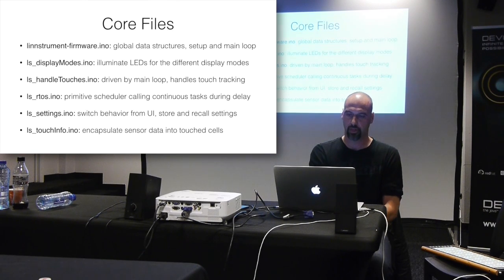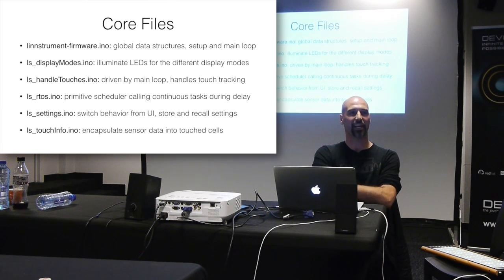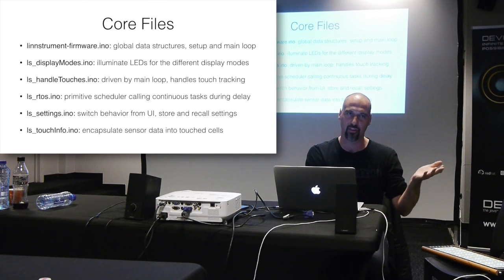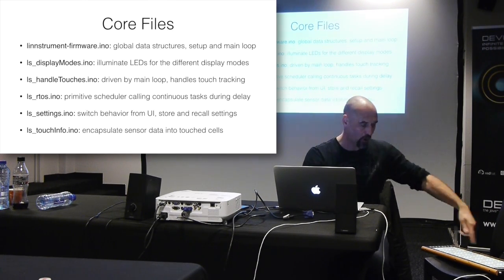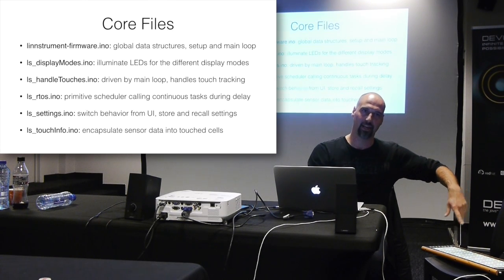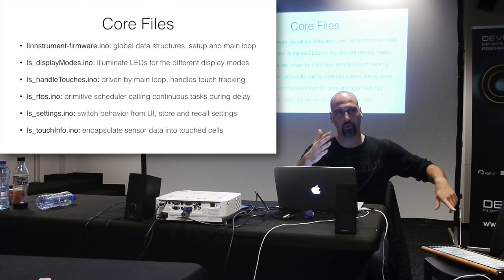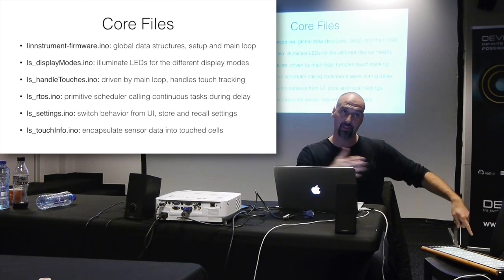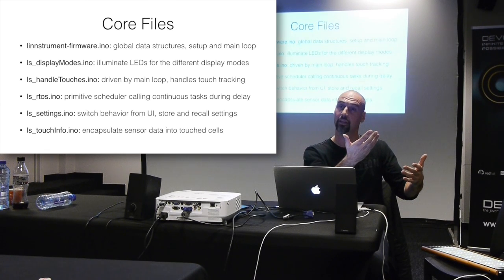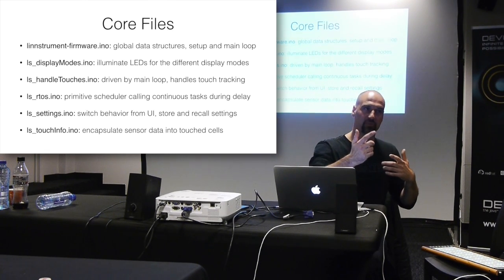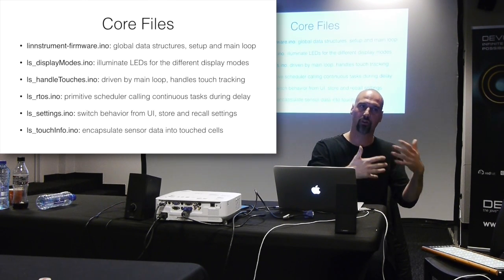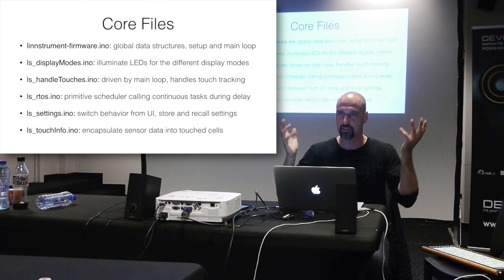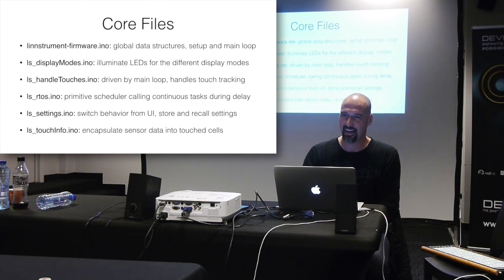Then we've got our primitive real-time scheduler, which basically hijacks delay functions. The delay function that you saw there, pretend that it's an Arduino one. Well, this is one that we wrote. It's like a regular delay function, but while it's waiting, it continues calling this global functionality. Okay, I have to wait for, let's say, 200 microseconds because the voltages have to stabilize, but in the meantime, I also want to update the LEDs because otherwise you're going to see it. Or if MIDI information has to be sent out, it has to be sent, otherwise the music data is going to be interrupted. So there's a bunch of continuous tasks that, like in a poor man's scheduler, is doing that, hijacking the delay functions.